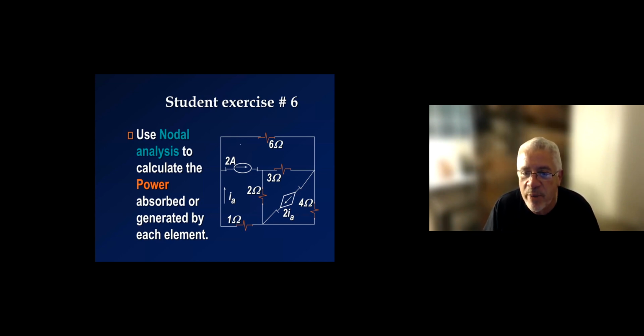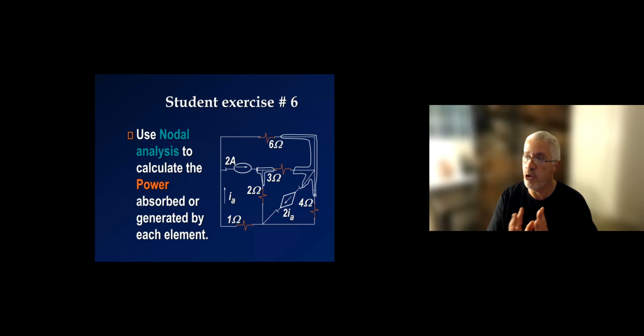Again, I still want to make sure that you have the nodes accurately. So if I start here, I'm going to say this is a node here, this is a node, and this is a node. Okay, so that's one node. If I start here, I'm going to say this is all a node, still the same node. Again, feel free to do this until you're comfortable with getting the nodes accurately, because if you don't get the nodes right, nothing else works.